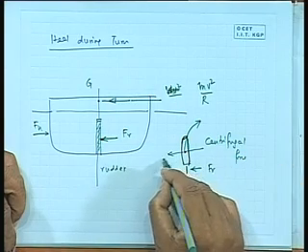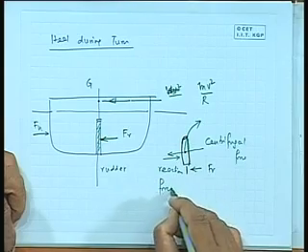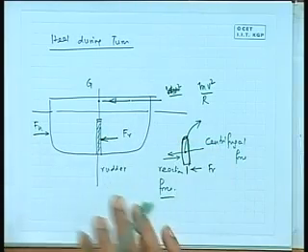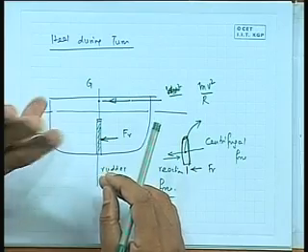And there is a reaction force to the hull. Now, I think I am not going to have time for this, but we'll start from here. What happened, interestingly, is that the interplay of this force will cause the ship to actually heel, and it turns out that the ship heels in the outward direction, which we will discuss. In fact, there can be a problem with how much it will heel during steady turning.